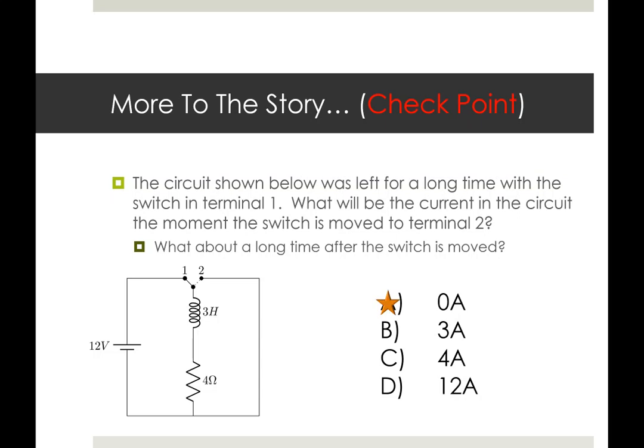All right, I hope you said that in this new situation, after a long time, there would be no current. This is conceptually the situation we looked at at the end of the last video, where current is going to sort of leak away and go down to 0, but the inductor just limits how quickly that will happen. But we do still wind up getting to 0 volts, 0 current in the circuit regardless. That current does leak away, but it happens slowly.